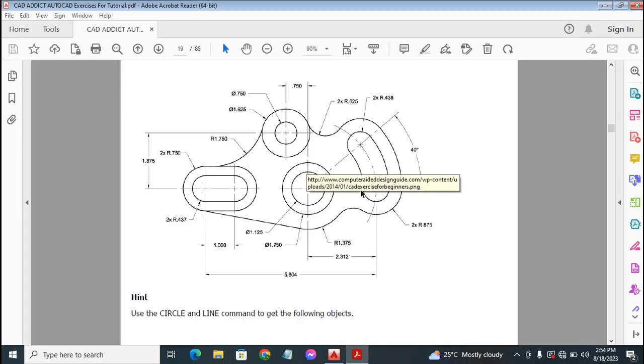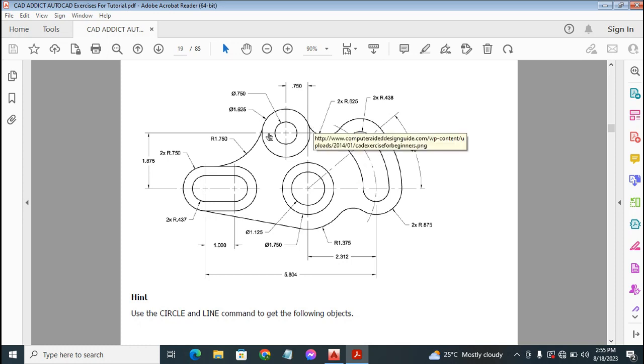So here, as you can see, to get the center point of this other radius here, we're going to get an angular construction line of 40 degrees. The point of intersection of this angular construction line on the circumference of the bigger circle produced using that construction line is going to be serving as the center point of this radius. Hope you understand what I just said there.